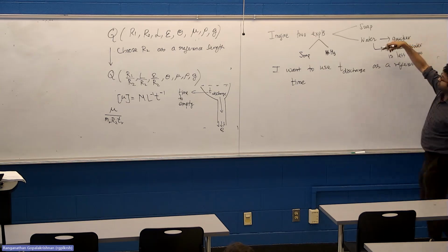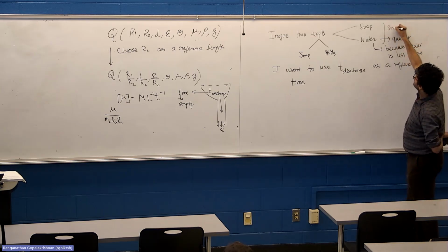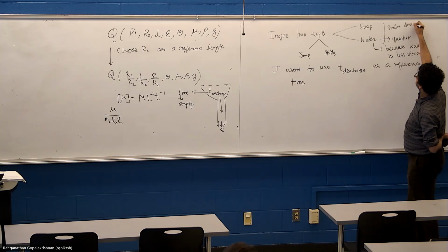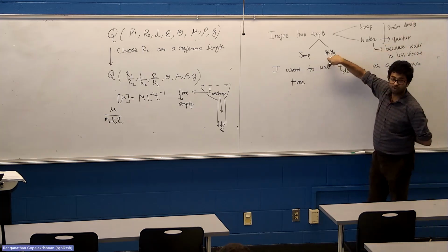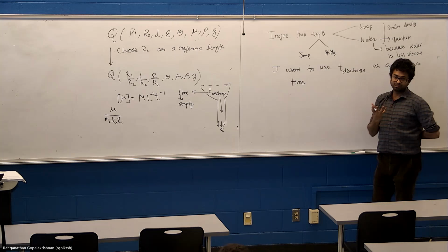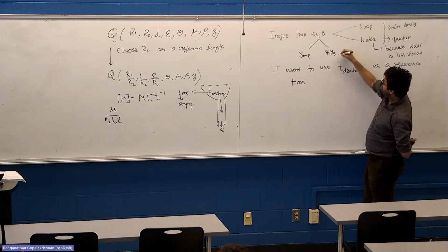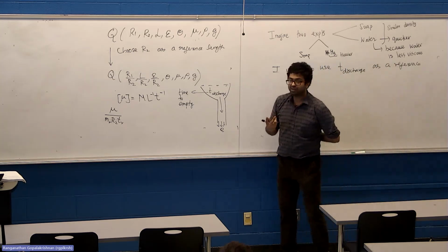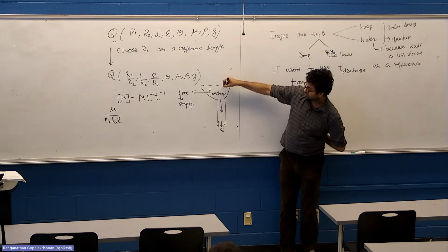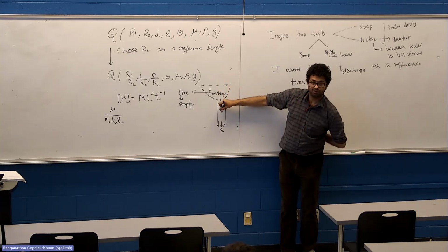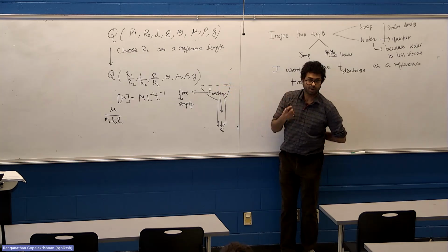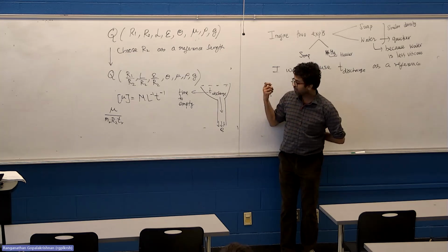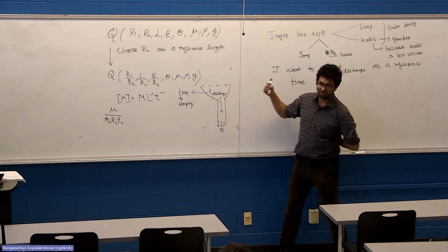These two have different viscosities, but they have similar densities. And between soap and mercury, which is the heavier liquid? Mercury. And why should it matter? Why should this problem have a dependence on density? Because the driving force for this flow is the weight of the fluid. If you had a fluid that's quite heavy, or if you somehow bring molten metals, that will drive a much faster flow because the metal is going to be heavier, like mercury.